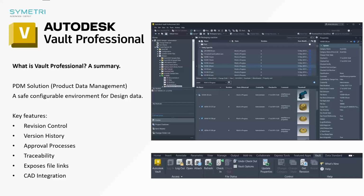Version history is more about keeping a record of all changes that occurred on a file. So rather than talking about the full approval workflow, we're looking at smaller changes, such as when a file is moved from one location to another, a file is renamed, a property is updated on that file, or a file is checked out, modified in a CAD application, and checked back into your Vault. All of those are file versions.